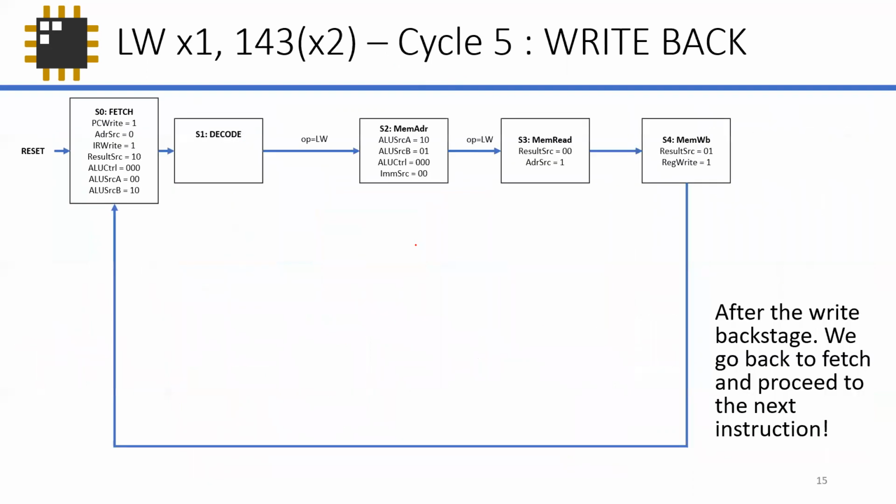So if you look at the state machine, bam, you're there already. You just have the right memory write back stage, feed it back into the fetch stage again, because in the next cycle, you start from, quote unquote, cycle one, or the fetch state, fetch stage. Okay. So it's pretty much simple. I think by this moment you're supposed to somehow grasp it already.